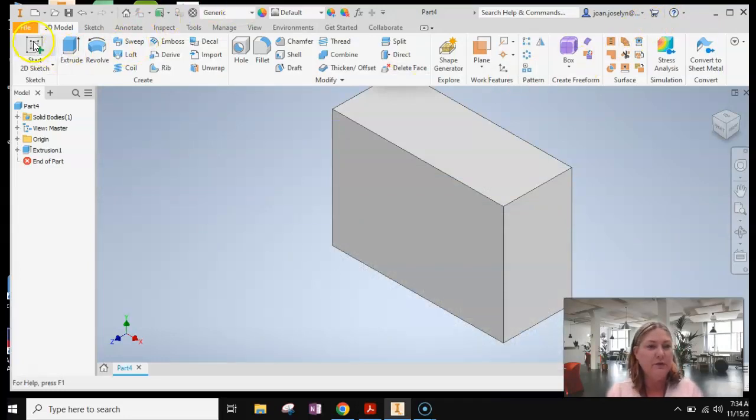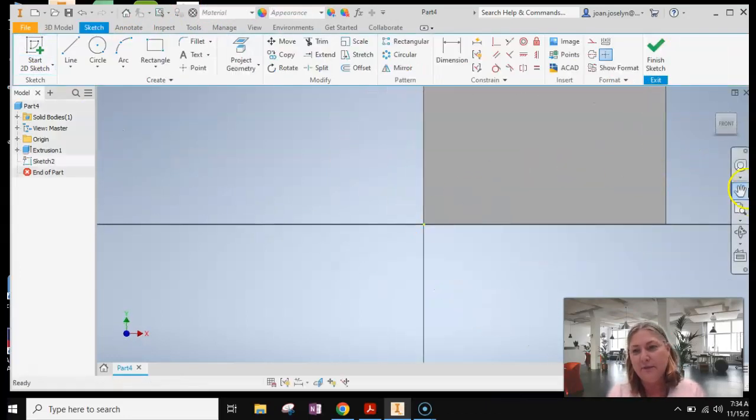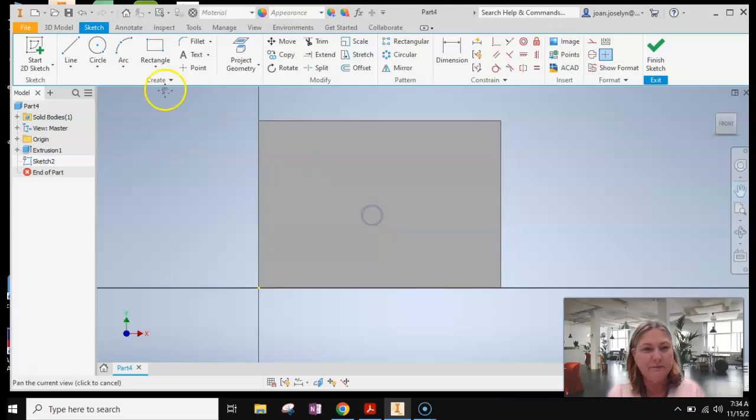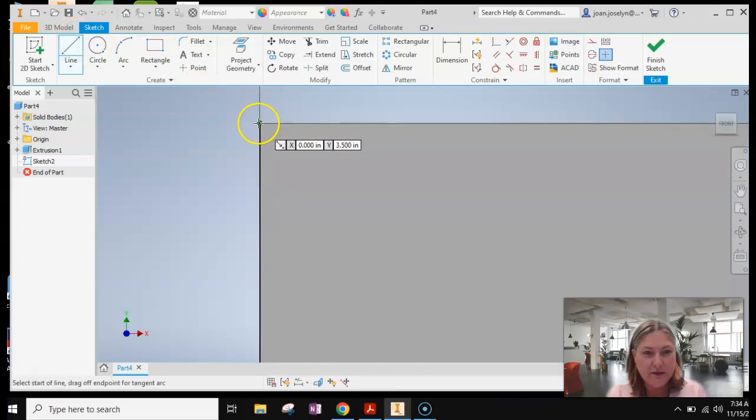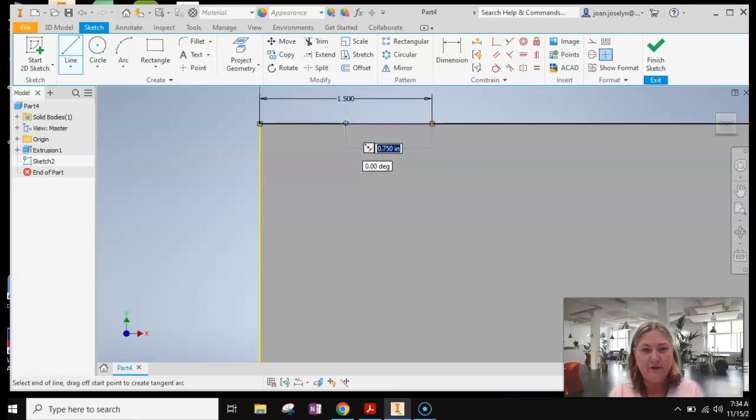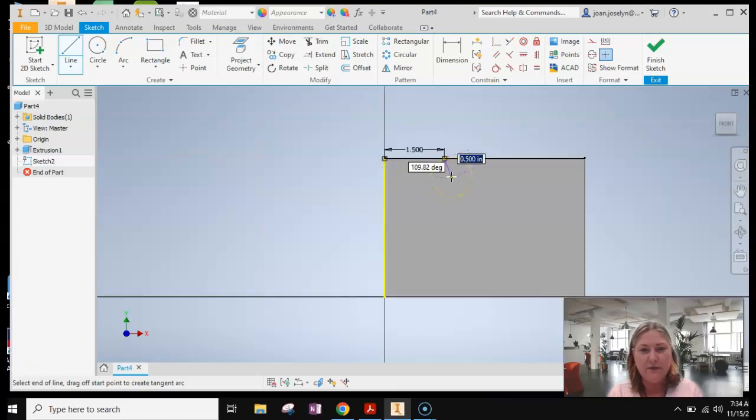We're going to do a new sketch, left click, click on the front face, not the edges, but the face, left click anywhere. Get it in front of us. And let's figure that out. So we said line tool from this edge, make sure you're clicking exactly on it. So that color changed, mine turned green. We said it was 1.5 or 3 boxes. So 1.5, enter. I'm going to scroll out. And then we decided it would be down here about, I think we said 1.